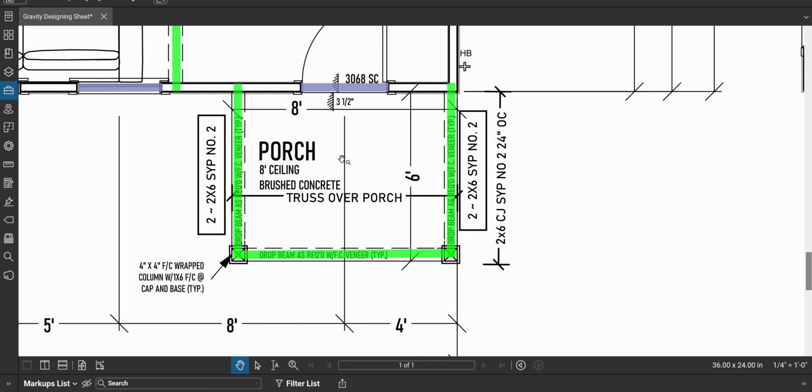Now, I happen to know because of what I'm doing that this beam is spanning maybe 7.5 feet. So it's spanning farther, but it's holding less. Now, if it was spanning the same and holding less weight, then I would think, if this one was already over designed and holding more weight, I'm just going to use it here because I know it's good. However, this is spanning farther, and the span of a beam has a large effect on how much it can hold. So we're going to calculate this one in the front.